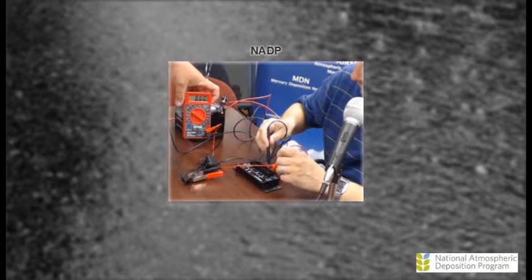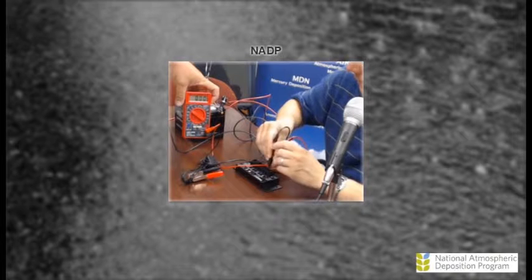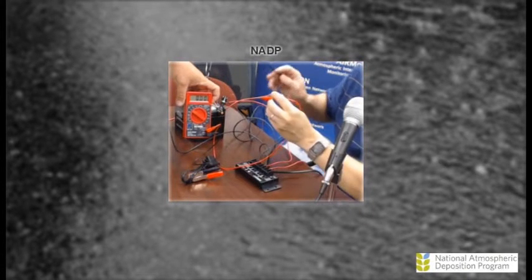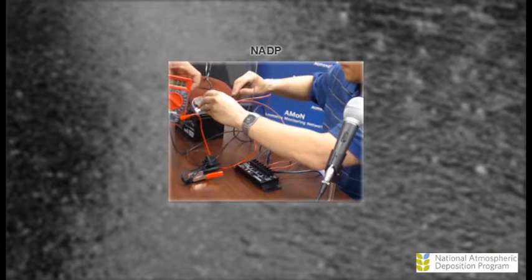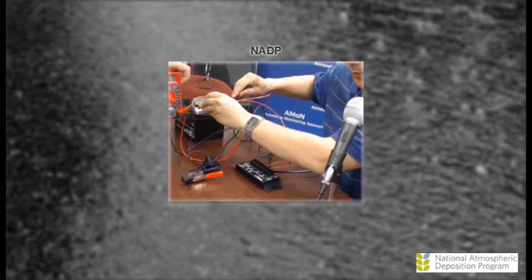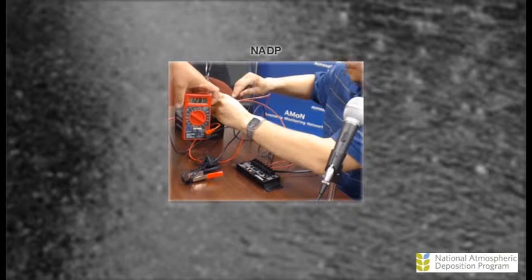And it should stay 0 or very low. And then for the check, it's again black to black, red to red. And we can see that it's at 0 power. Just for verification, I'll show the lead at the battery. We can see that's reading, it's just slightly off camera, let me move it over my way. Okay. Yep, we can see that's reading about 13 volts.